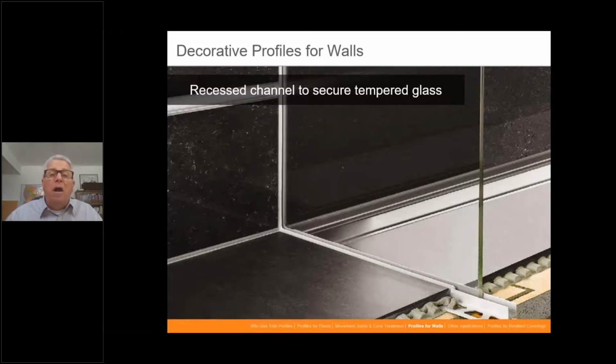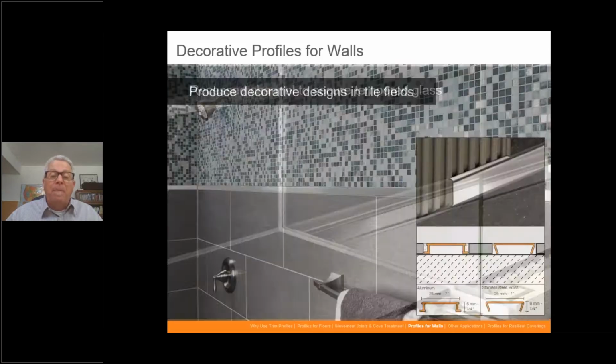And bear in mind that if you have waterproofing in here, because it is a wet area, it's nice because the glass people don't drill any holes through all your waterproofing when they come to install the glass. They just simply set it in the track with some sealant and some of the small bumpers that keeps the glass from chipping as it goes in, and it makes for a very, very clean application between the tile and your splash guard.